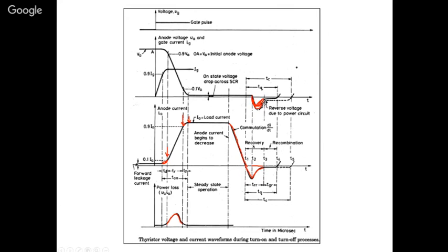So we have to take care what inductor value is connected in our gate circuit. Why do we connect this inductor? That is di by dt protection. When there is a sudden rate of change of current, your device will get damaged. So to limit that, you put an inductor there which will limit the flow of current. But because of that inductor, when we are turning it off, there will be a negative voltage that may damage your device.